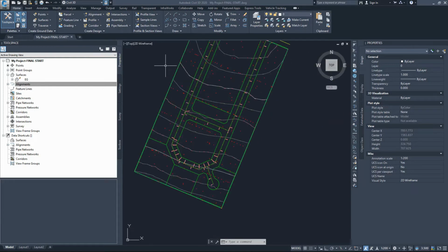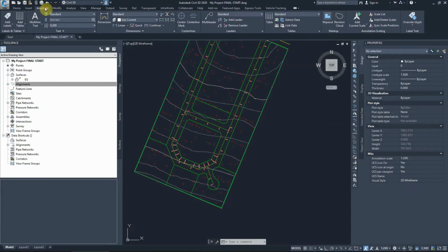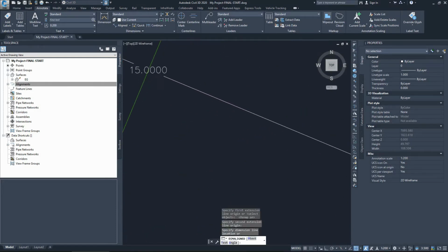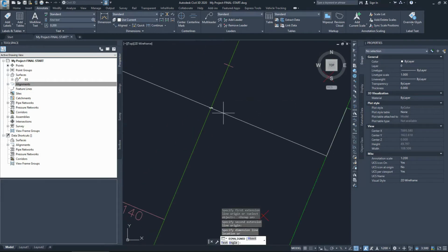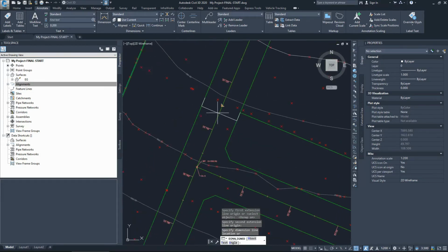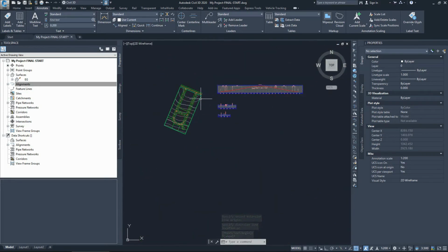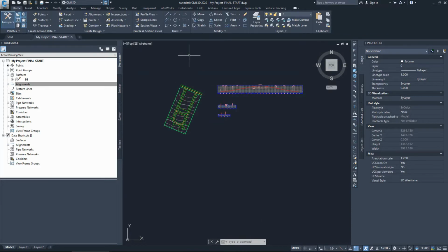I'm looking at our project. One of the quick things that we should always do on a project is try to measure how much road reserve we're dealing with. If I measure the width of our project, I found it's exactly 15 meters. So our road reserve, that means the edge of the boundaries of the road, is about 15 meters. So we need to create a cross section that will be suitable for 15 meters.